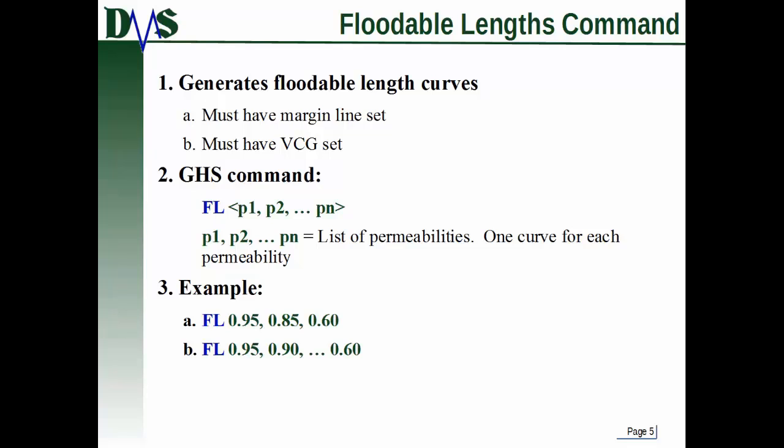The nice part here about the floodable length curves that I also have to define for you is you don't need to actually have your compartments defined in the GHS model yet. You just need to have a hull definition. And that's why we're doing it at the preliminary stage, where you might know what your hull looks like, but you probably don't know what your internal compartmentation is. And so the floodable lengths command helps you figure that out.